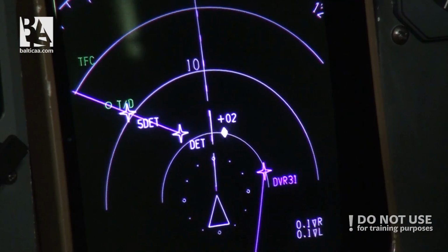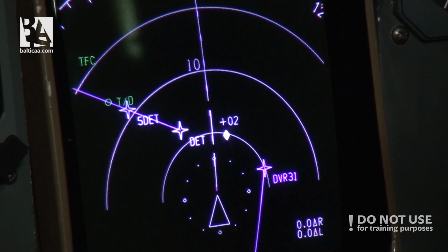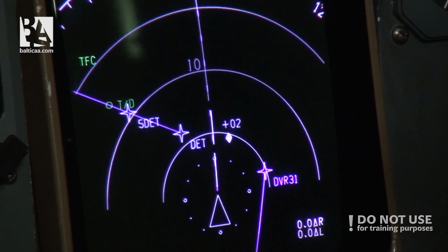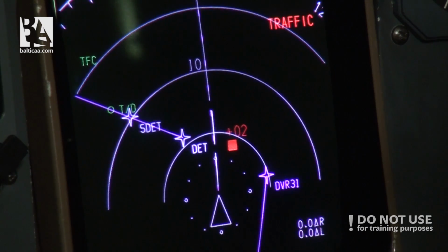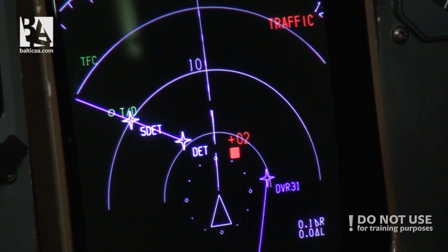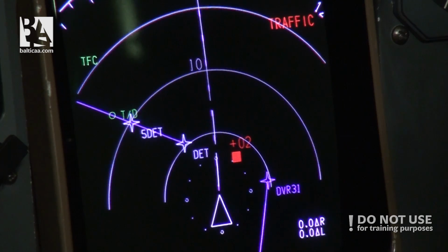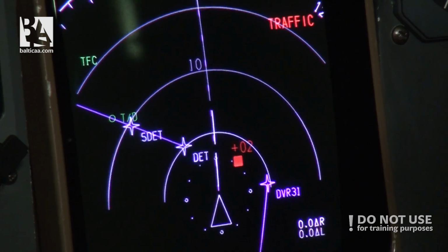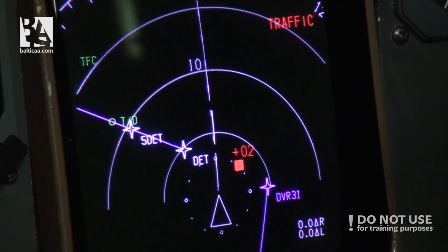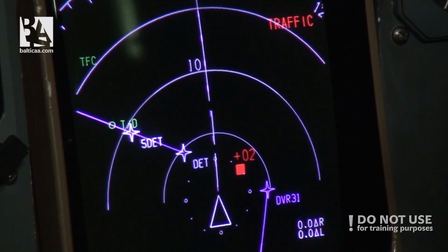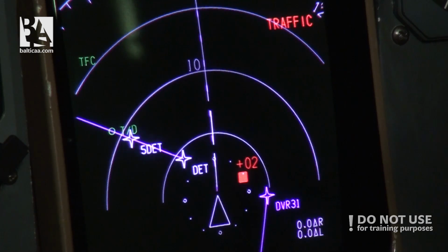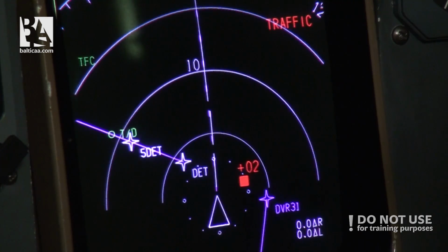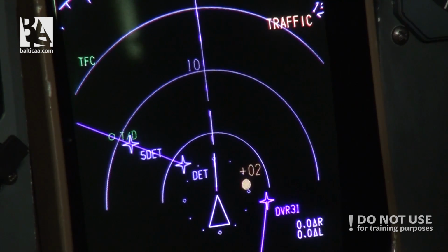If you lose your IRSs, you can revert to ATT mode and acquire a heading and attitude on your primary flight display, and you will still be able to use your heading bug, but the autopilot will not work. The IRS knows by itself where true north is and can sense the accelerations and movements of your plane, so you will always keep attitude and heading information. So the answer to your question, yes, if IRS is working.